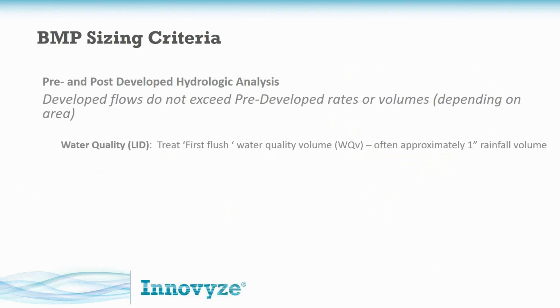And you can even assume, with a concentration of suspended solids or total nitrogen, total phosphorus, fecal coliform, even trying to track those pollutants, we might still assume, all right, any flow that, let's say, drains through a rain garden or a bioretention facility, we're going to assume 100% TSS is removed. So even then, it's still a kind of percentage removal, or just, if you can get it through a facility, then it is okay. So that's how we usually size our water quality facilities.